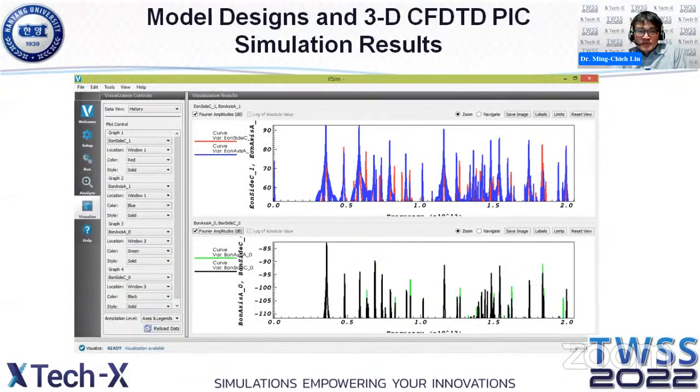So this shows you the wideband excitation. But remember I told you that you have to pick field components. If you want to study LSE or LSM, you should choose different components to excite the wave. Here I focus on LSM. As you can see, there are a lot of normal modes excited. There are a lot of higher order modes, as we know, but we are interested in the LSM11 mode specifically.